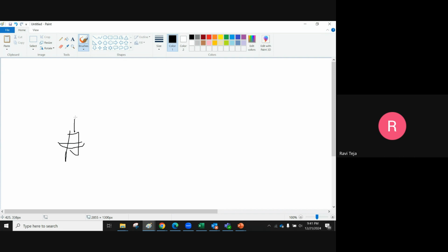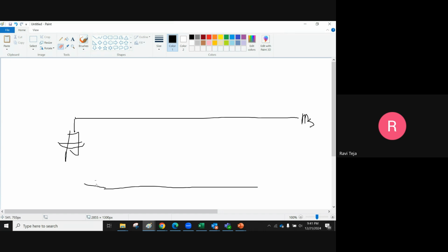So I have my antenna on M3. For antenna, what I told is, if I have any long metal this way, I will chop this region and then I will use a higher metal. So I will use this higher metal. So if it is M3, I will use M4.